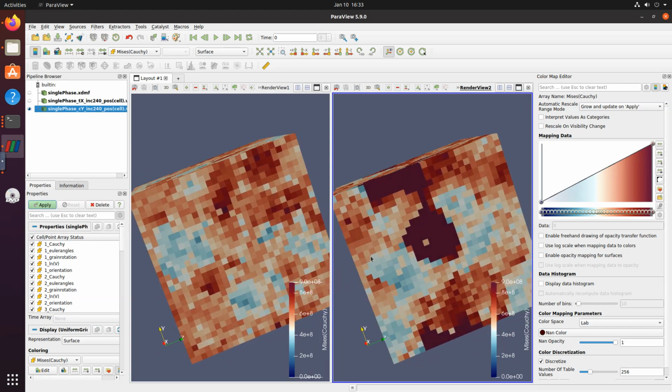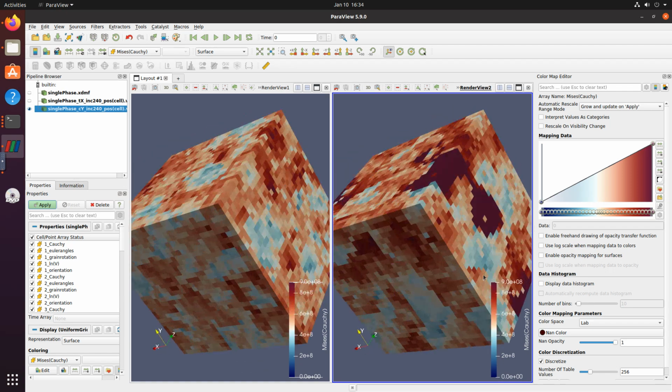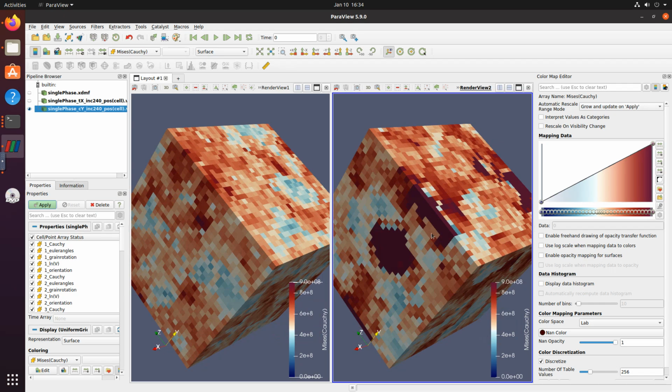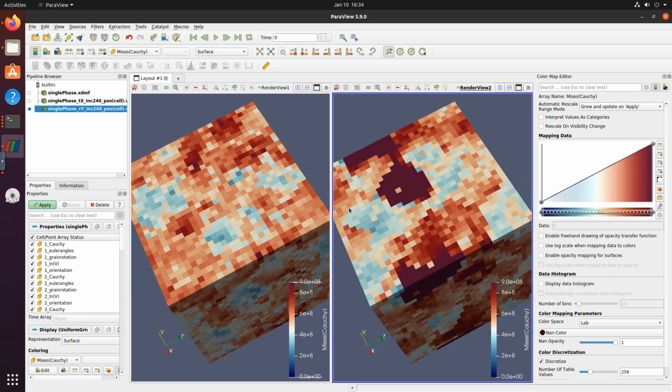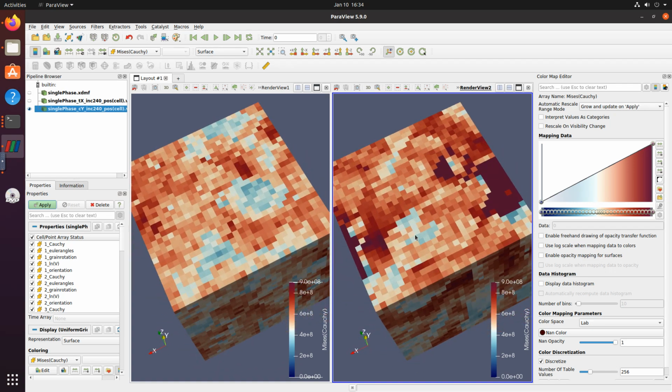You see, right? So there are some grains that are martensite, and what we see is that the stress in them is extremely high, right? And then, for example, when we compare the results with the previous one, so this is one grain, this is also the same grain, but now the stresses are a little bit higher because it is very close to a martensitic grain here, and similarly the stresses here are very small, but now the material is quite close to a martensitic grain, and therefore the stresses are relatively higher here as well, right?